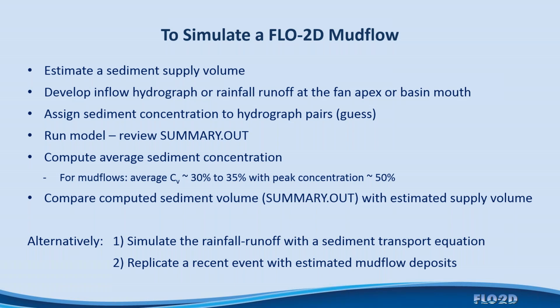This is more or less a guess. We're going to look at this in detail here in a second. Then I'd run the model. I'd review summary.out. I'll show you how to compute the average sediment concentration from the information in the sediment.out file, summary.out file, and then compare the computed sediment volume with the estimated supply that you made.